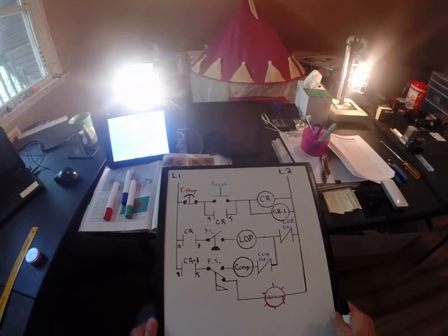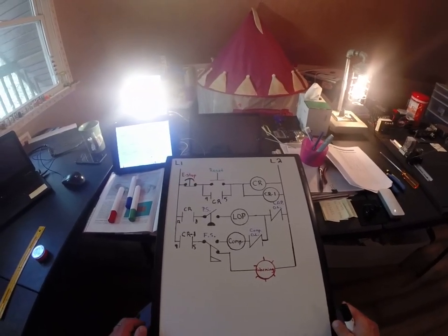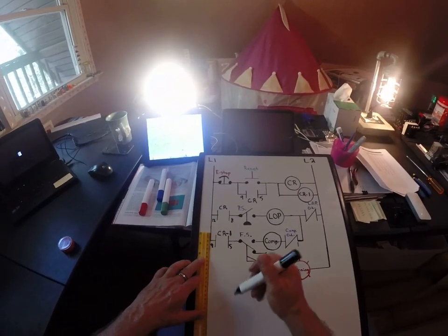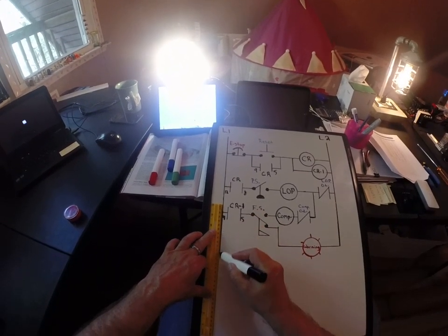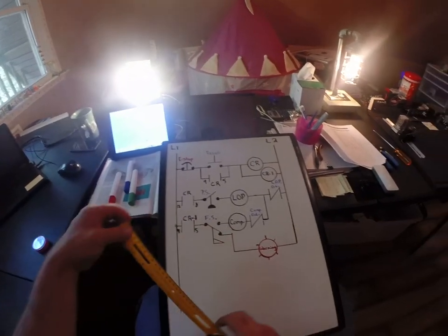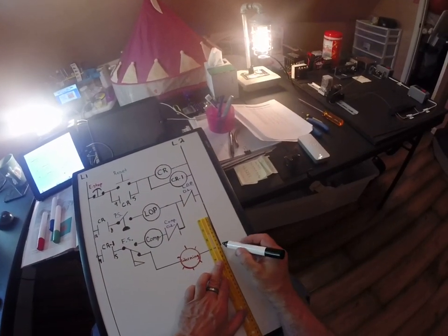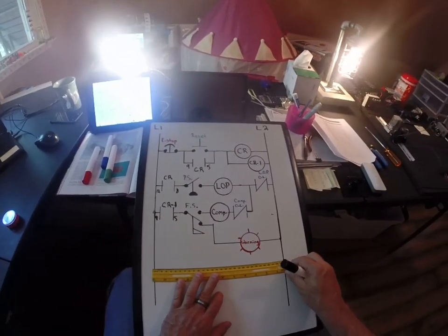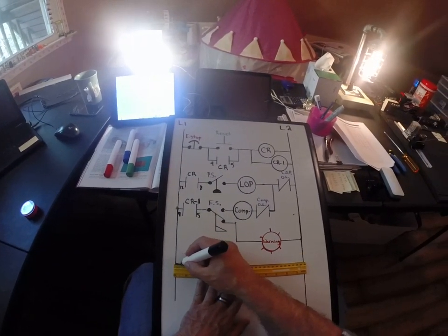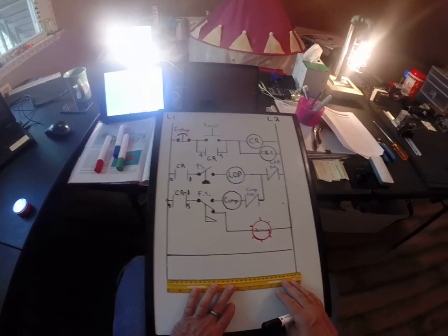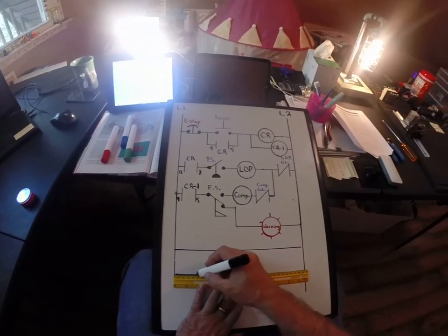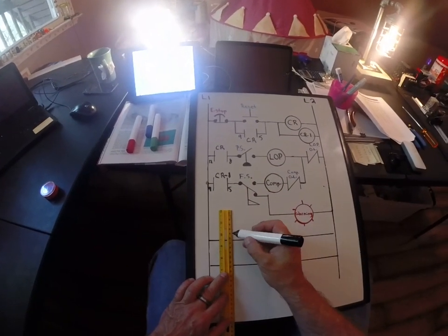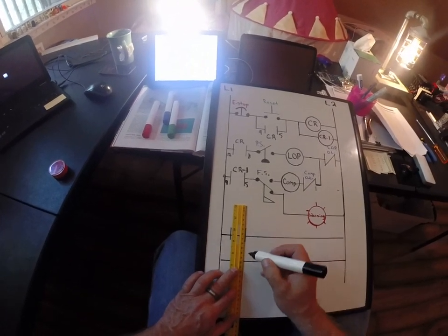The next thing we want to do is be able to add to the circuit an indicating light when the lube oil pump is running and when the compressor is running. That's simply just by extending this line. We would want to add that light in there. We extend this line. We come across here. This is a very simple way of adding to a circuit. And what we're going to do now, we have unswitched power on the left, which obviously is there for us when we need it.